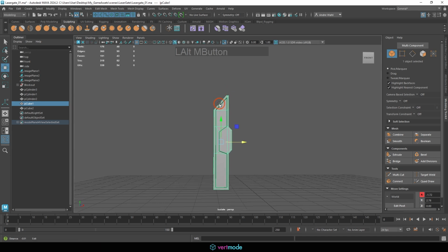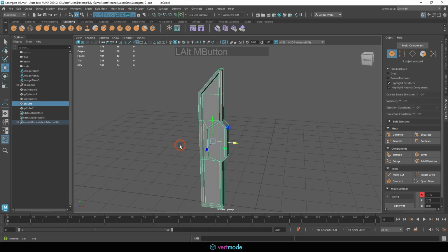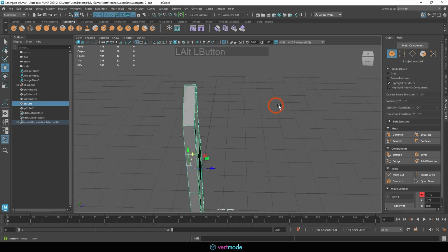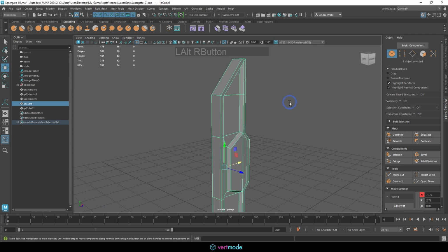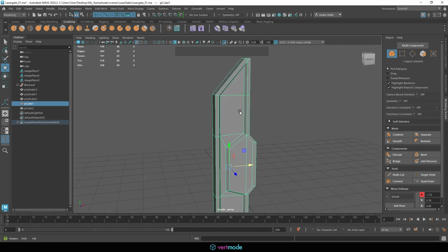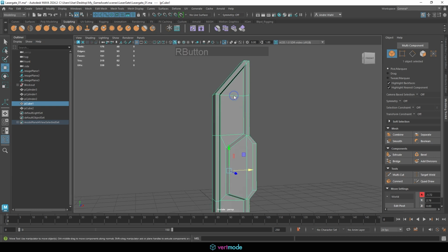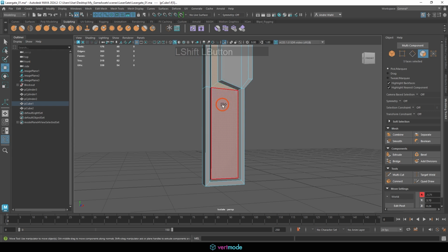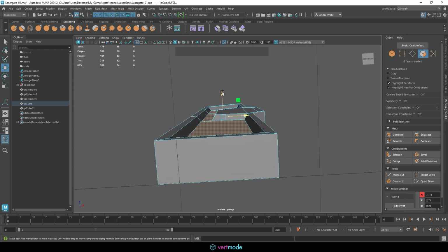There's a lot of ways we can add in these smoothing edges, but the way that I prefer with something like this is to simply use a bevel as much as possible. You can do this before or after you mirror, which is another thing to point out. And we also might want to adjust the depth of this before we do. The depth of this can affect how it looks in the normal map. This is pretty deep. I might want to make this a bit more shallow.